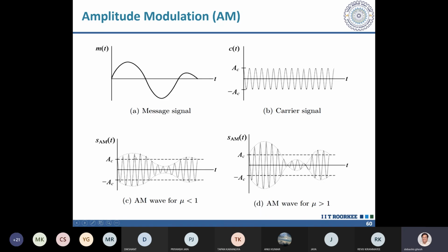Now when you demodulate, you don't know whether it was the message or whether it is noise. The amplitude has suddenly gone high like this. Then the amplitude is low. Again somewhere here, because of noise, the amplitude has gone high. Wherever the amplitude is going high due to noise, the receiver doesn't know whether it is due to the noise or whether it was actually the message.